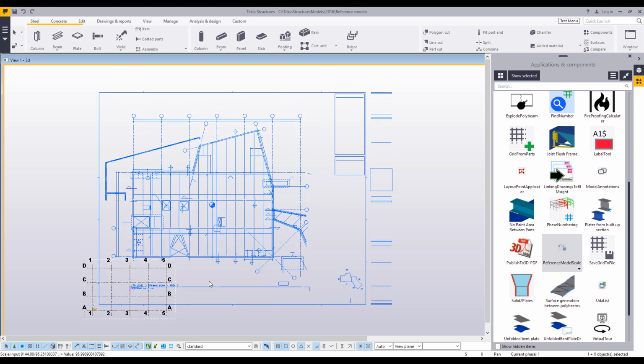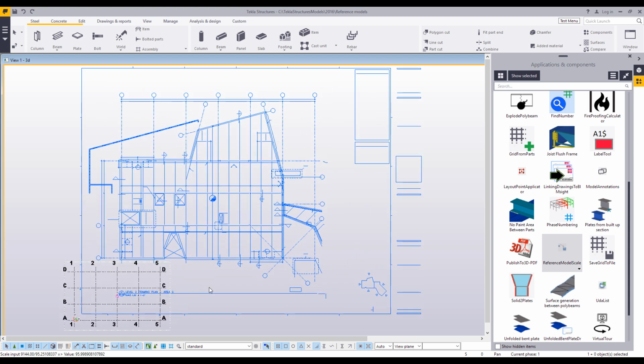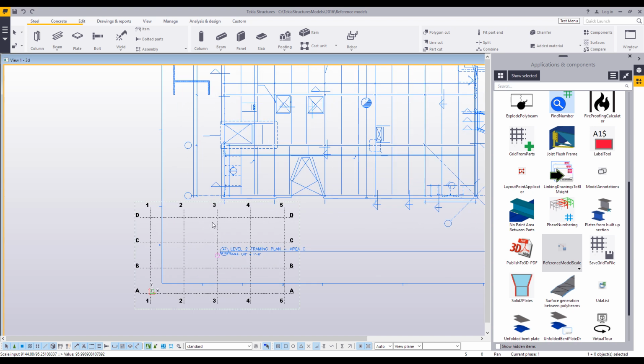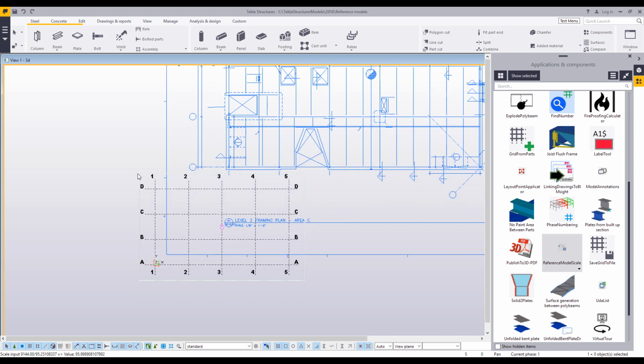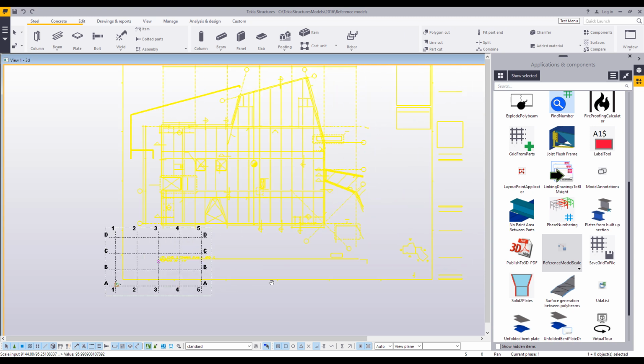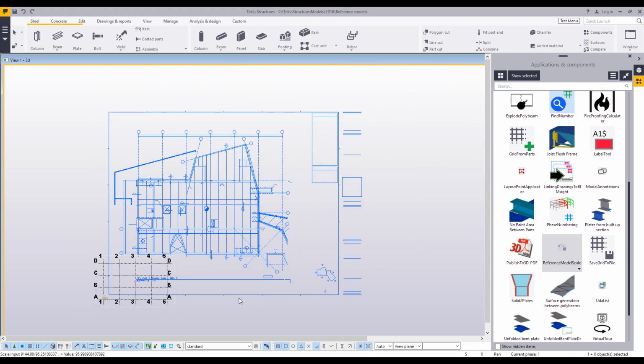Now, you might notice that at first I can't see some of the things I could originally see. I can't see the text. There's certain details of it that are missing. Well, that's because of one of 2 reasons. The first main reason would be the work area. So your model has this dashed box around it called a work area where you can stretch that up, and with a regular structural model, you can increase what you see or decrease what you see.